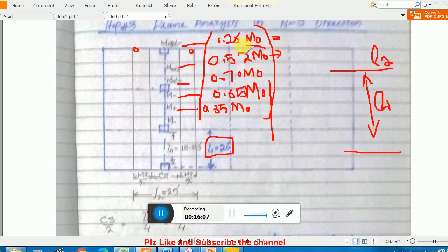The whole moment which you got from this figure will be distributed, at 60% in the column strip, while the rest, 20% will go here and 20% will go here.